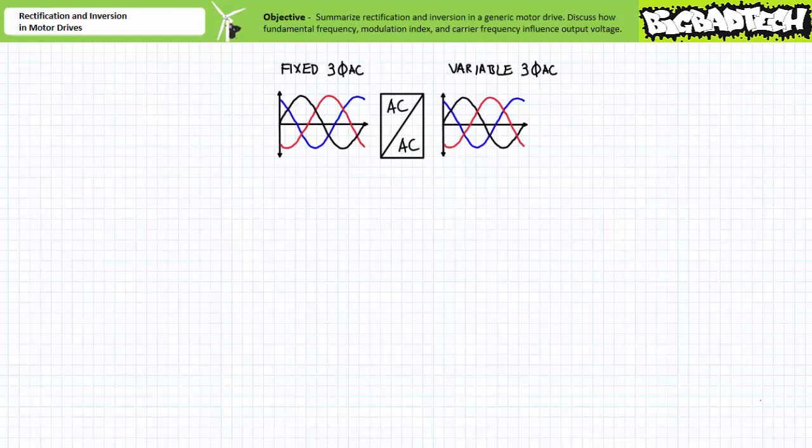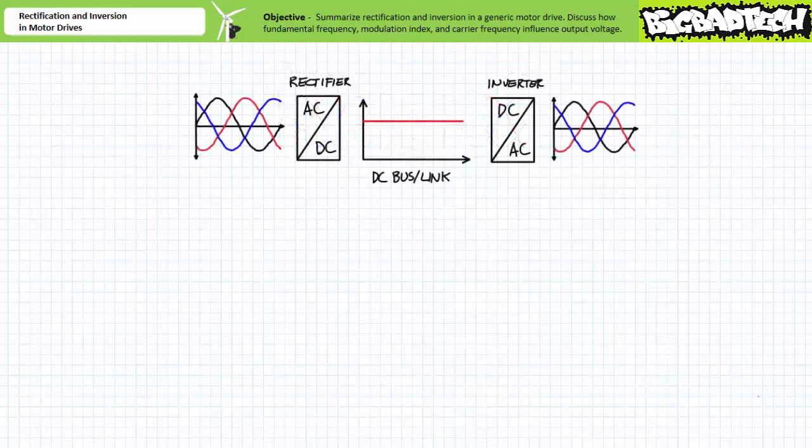If we were to picture the motor drive as a magic box, three-phase AC with fixed magnitude and frequency comes in, and three-phase AC with a different magnitude and frequency comes out based on motor drive settings established by the user. At this level of sophistication, a motor drive is therefore a power electronics device known as an AC to AC converter.